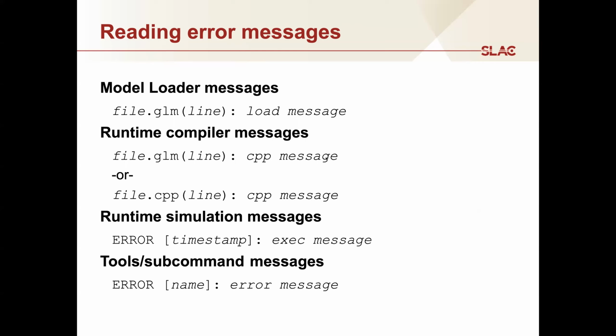And whatever the message is would be coming from the compiler, not from Gridlab-d. So that would be generally a language issue rather than a modeling issue. Once the simulation starts, you can get messages from the simulator. Now, generally messages are in the form of a tag, which indicates whether it's a warning, verbose, debug, error, fatal, exception, etc.